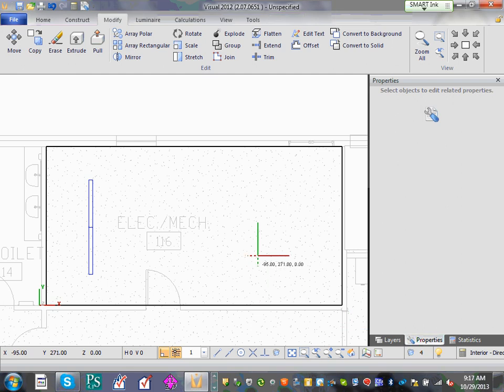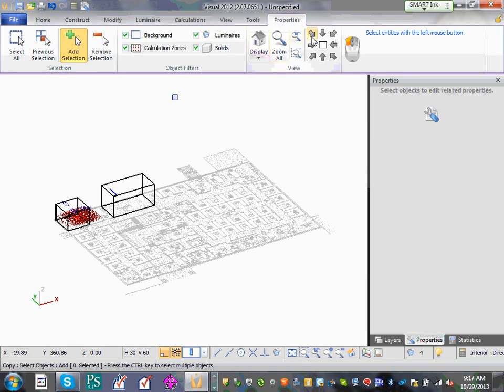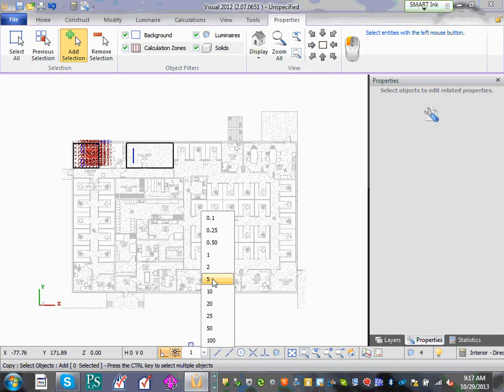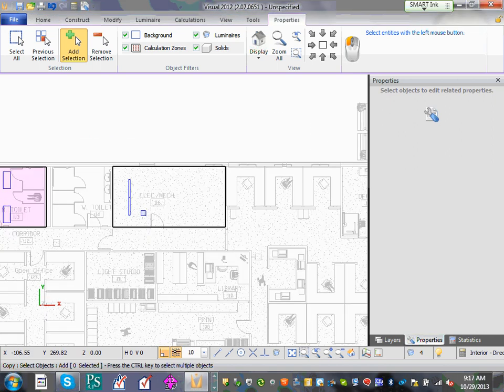And we're going for 25 foot-candles in here. Let's try. I'm going to grab the 10, because I selected copy. Now I'm going to try to copy this thing on a 10-foot center and see if we get close.